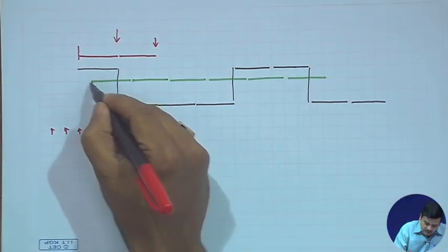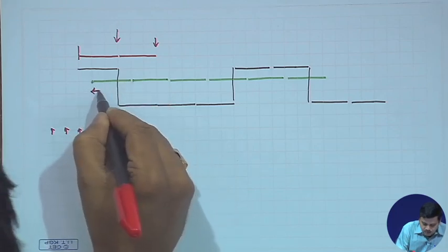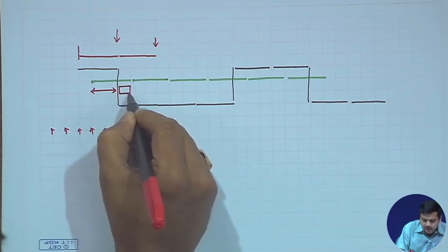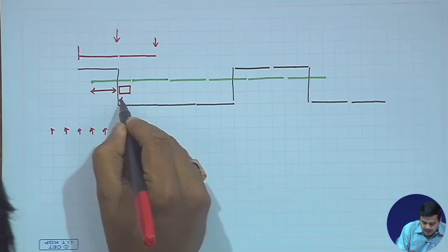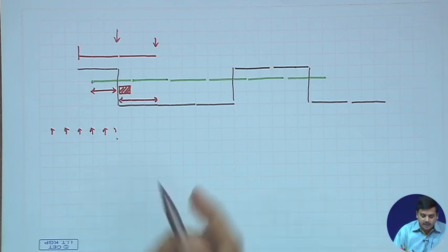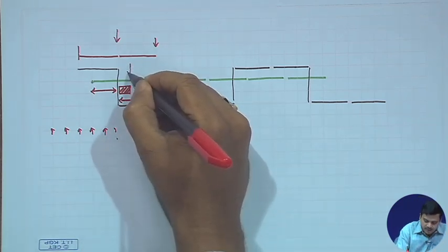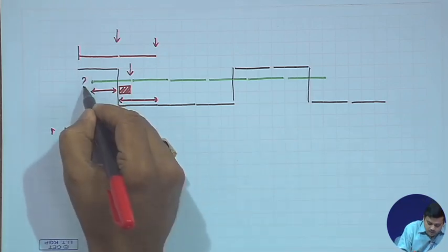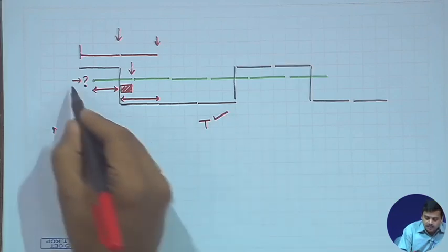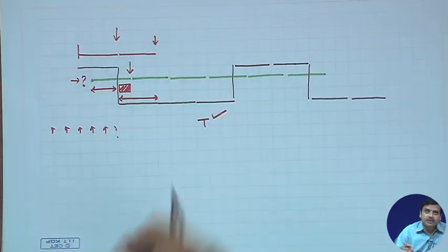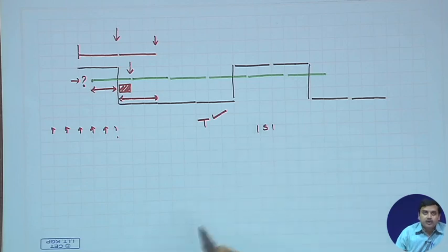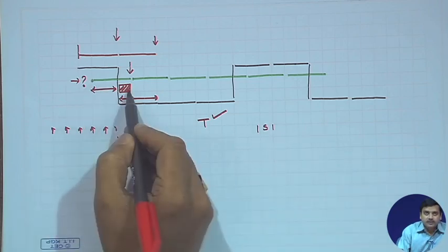So, when you multiply by g(t), you are taking a small part of the desired signal and you are taking additionally the interference signal. So, this is the second symbol and you are taking this portion of the second symbol at the output of the matched filter, because you are sampling at this instant of time, because you do not know the starting point. So, although your T is perfect, but the delay at which to start is not known, the exact sampling instants are not known. So, what we have is inter symbol interference, two symbols get interfered.